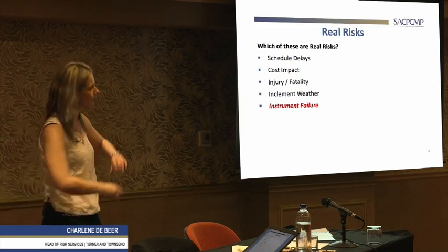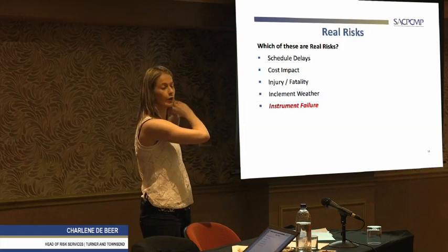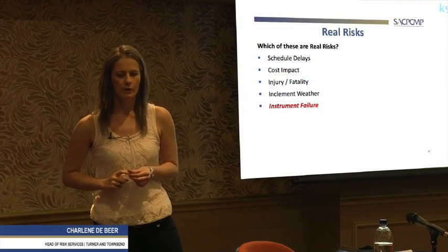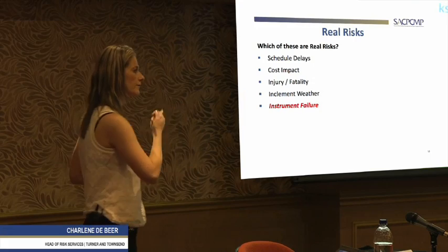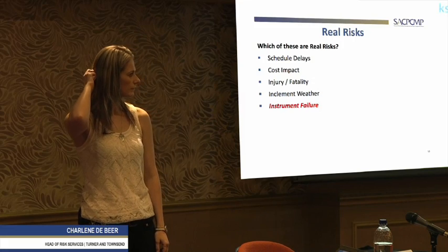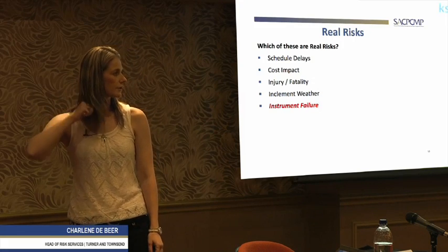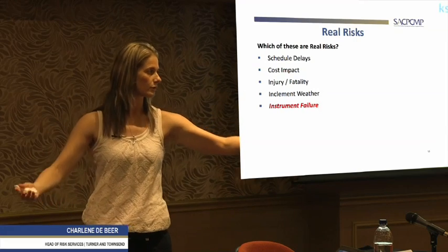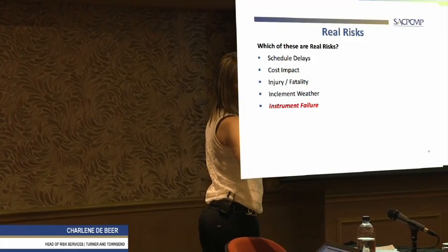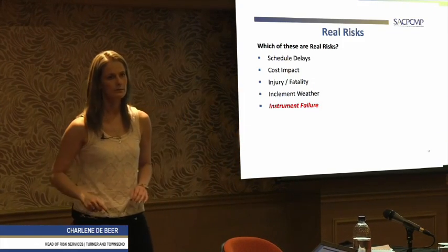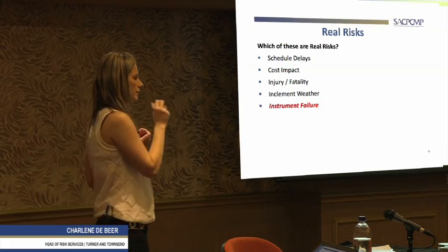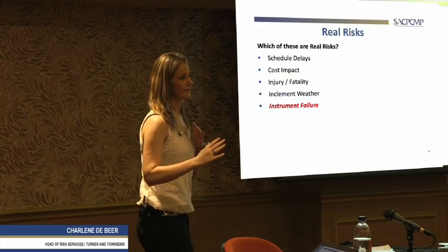It's a cause. It's because it rained a lot, or the wind is too strong and we can't lift because the wind's above 15 kilometers per hour or whatever the OSH Act says. So what is the risk? What do we face if we have adverse inclement weather conditions? It could bring civils and earthworks to a halt on site, for example. If we decide not to mitigate and say we're going to weld in cocoons, because we can weld in cocoons, we might say welding could be affected. The real risk isn't the inclement weather, but are you guys understanding what I'm saying?